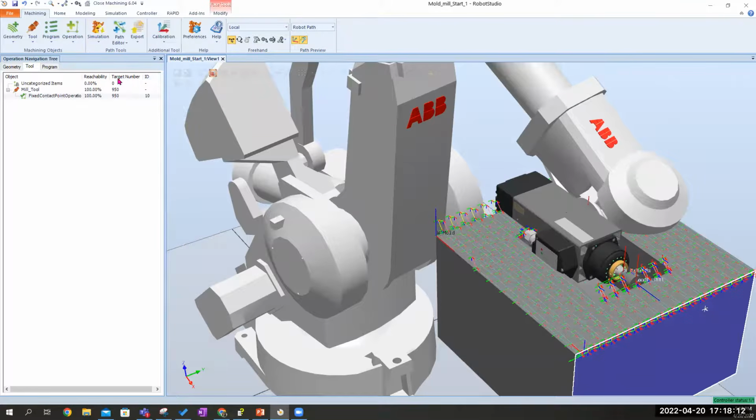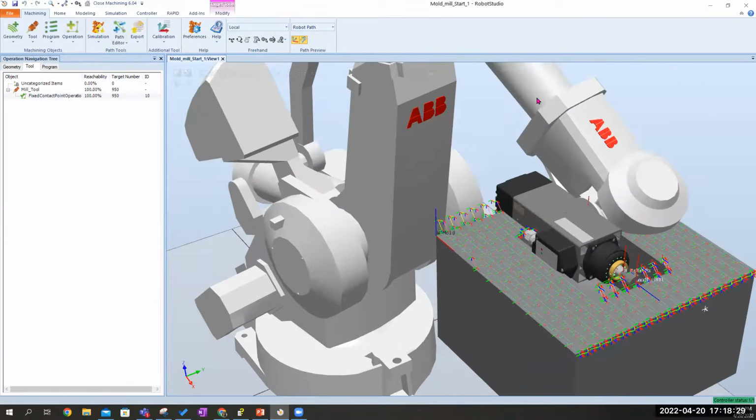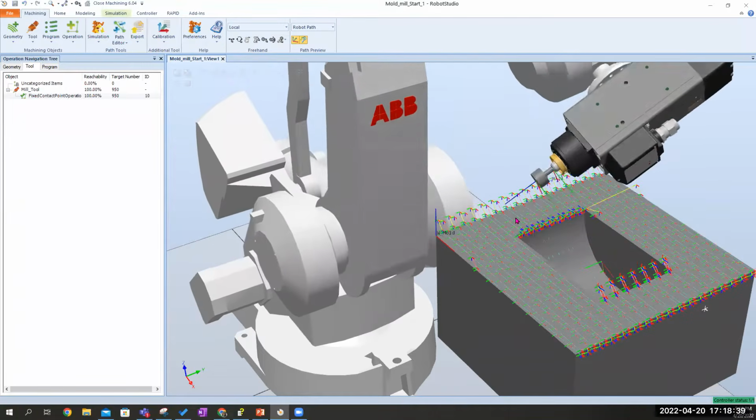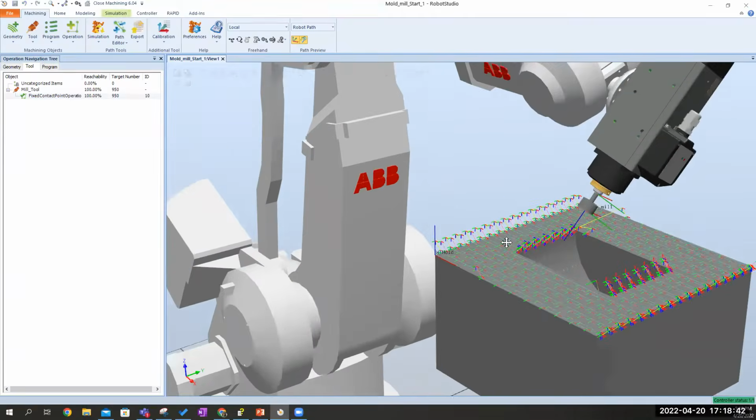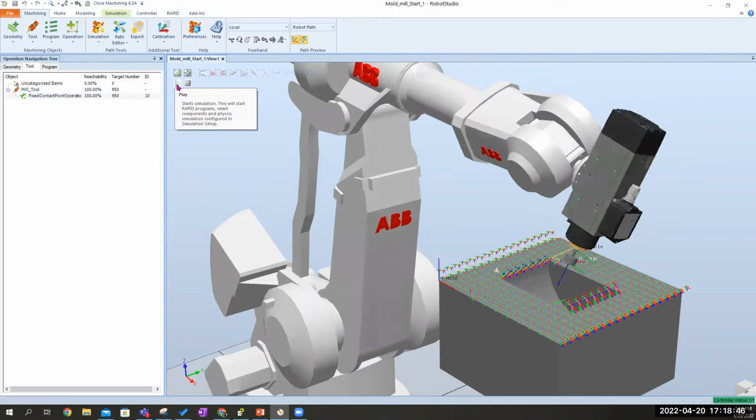And let's, now if we want to, we could go to the path editor and we could check it all out to make sure if there's any changes we want to make, any velocity changes or instruction changes or anything like that. We could make them right here for every point on there, but there isn't because I think it's beautiful. And now it's ready to go. So we could export it and bring it into another program, or we could just actually run our program in simulation mode. So there it goes to home, takes a second, and runs our program.